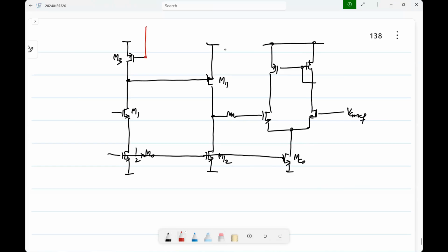And this connection completes the feedback. We of course have the capacitors used for the differential op amp there. So, there are 3. This is basically like a 3-stage op amp in unity feedback. Okay. So, to make the response well behaved, what do you need to do? The 3-stage Miller op amp, how many capacitors did it have that you deliberately introduced? 2. So, where should be the other one? Right. Between?